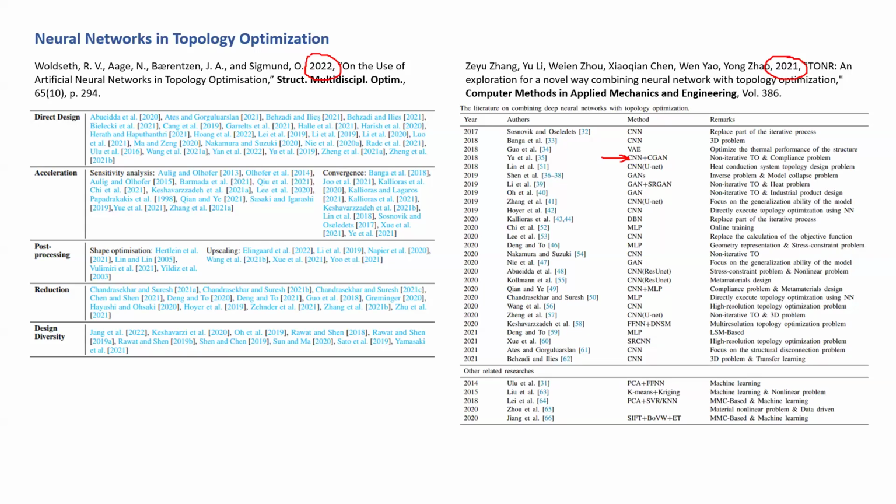And these applications are for generative, non-iterative topology optimization. So that's like one family. And then the other family is the use of multi-layer perceptrons. And with the aid of automatic differentiation, they just ease the cost of the sensitivity analysis, and that helps topology optimization.